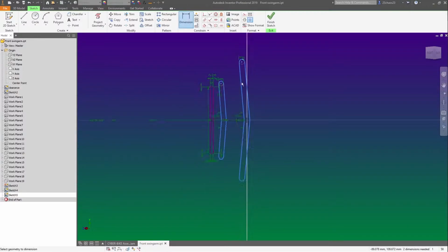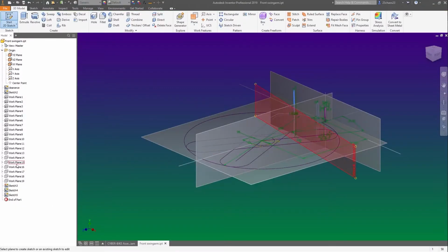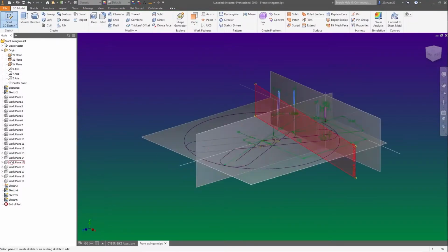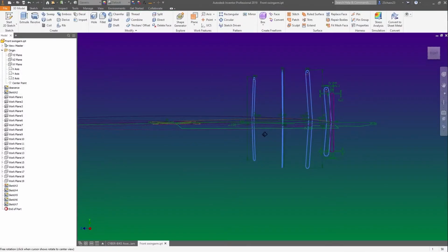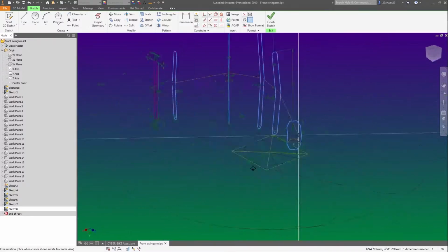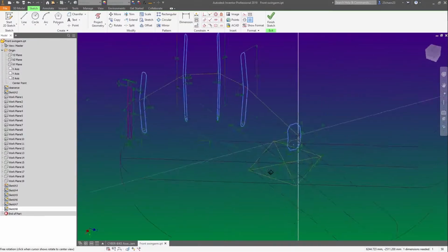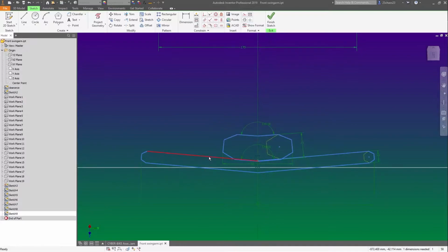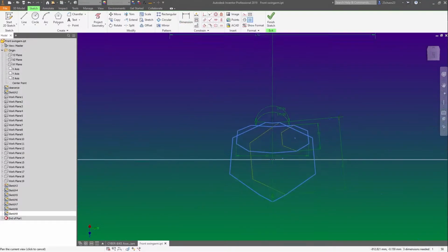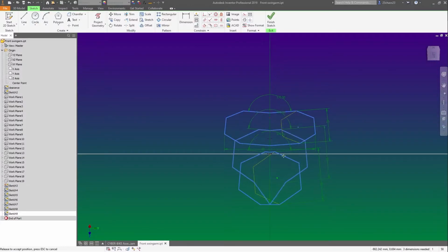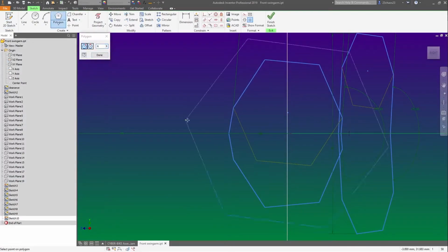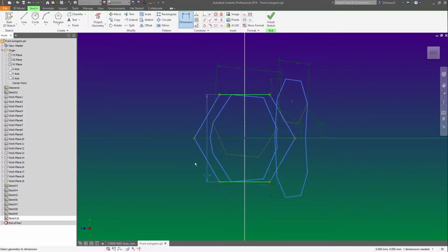Now, to get this to work better than the previous ones I've done, I think I was just trying to be too fancy and do too much. It was too complicated and it ended up screwing it up. So what I'm doing here is I'm using the same sketch, just copy paste, and then I just adjust the thickness and the cross-sectional height of each one of the sections, so that you get that tapered sweep down to the front where it connects to the wheel. And this turned out much better than the previous attempts, because you could just use the same sketch, so it had a much more unified profile going all the way through.